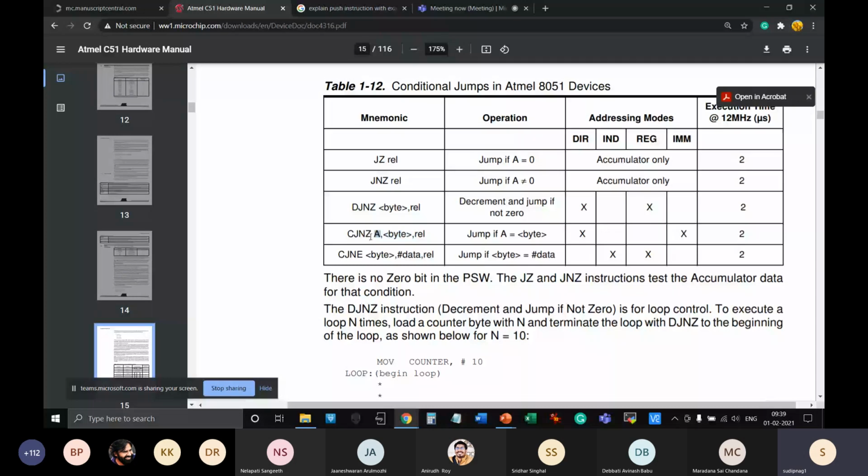What do we mean by compare? First of all, compare means whether they are the same or not, right? Whether same or different. Now how does a microcontroller find a comparison result? It actually finds it by doing a subtraction in the background. So you have 8-bit numbers and the microcontroller or processor simply subtracts those two values, and it doesn't store the result. That's the difference between subtraction and comparison in microcontrollers.